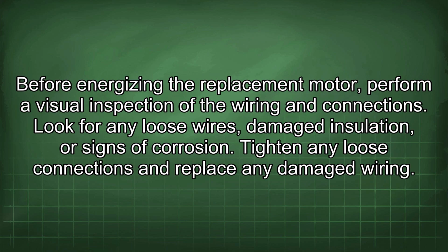Before energizing the replacement motor, perform a visual inspection of the wiring and connections. Look for any loose wires, damaged insulation, or signs of corrosion. Tighten any loose connections and replace any damaged wire.